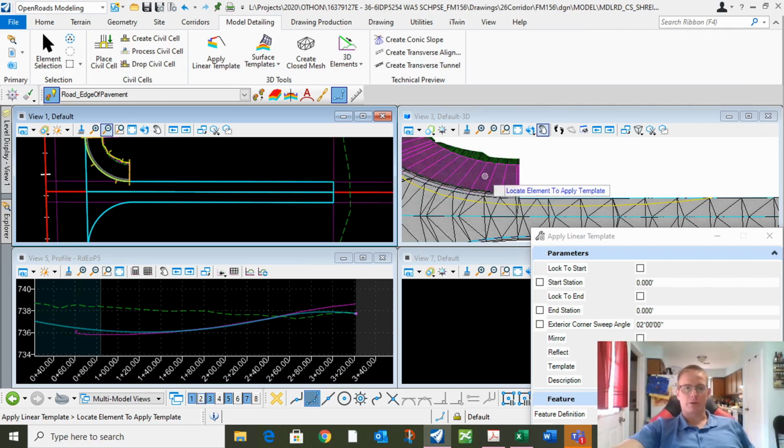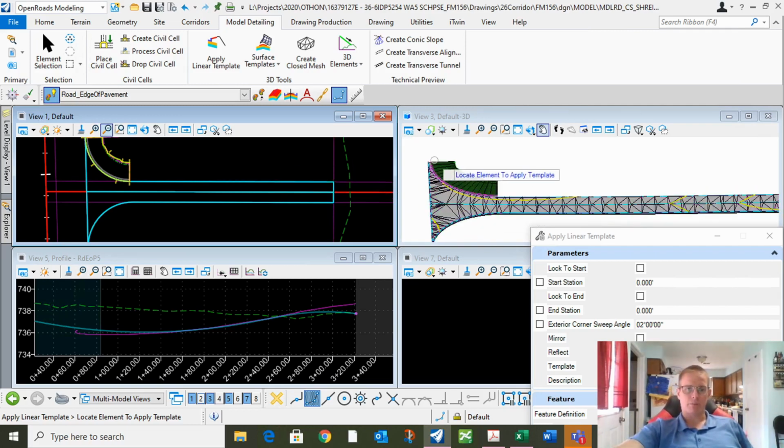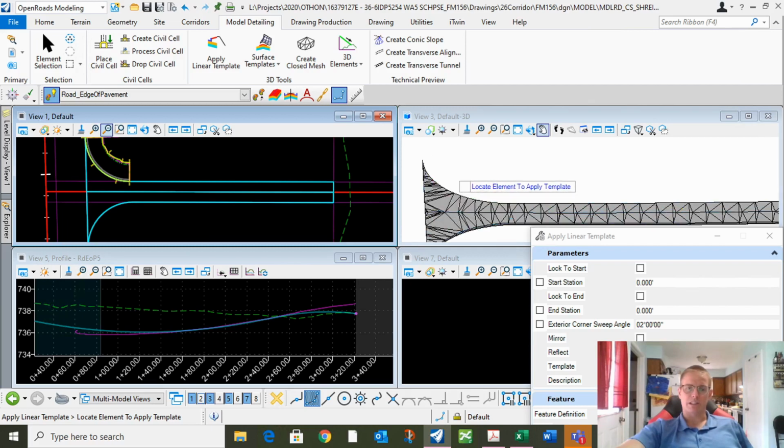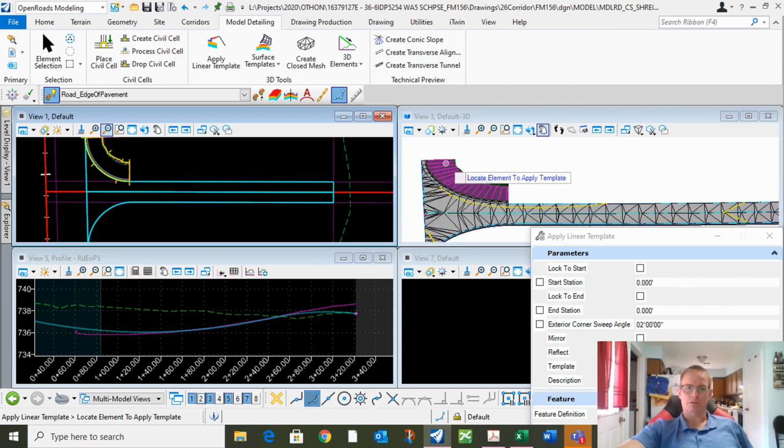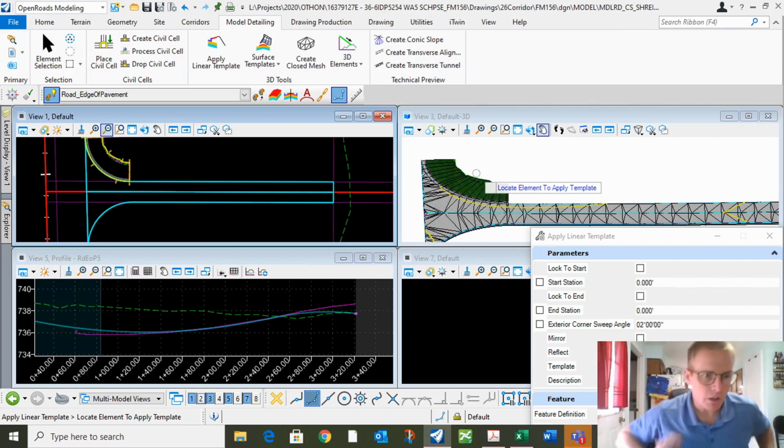We'll change this later, but basically we want this to match up with the main lane sidewalk and buffer, and that's why it's so large. I'm not doing the sidewalk around here, so I'm just leaving this area flat. I'm not modeling the curb ramps at this time, so just showing a flat area that the curb ramps can fit into should be enough.